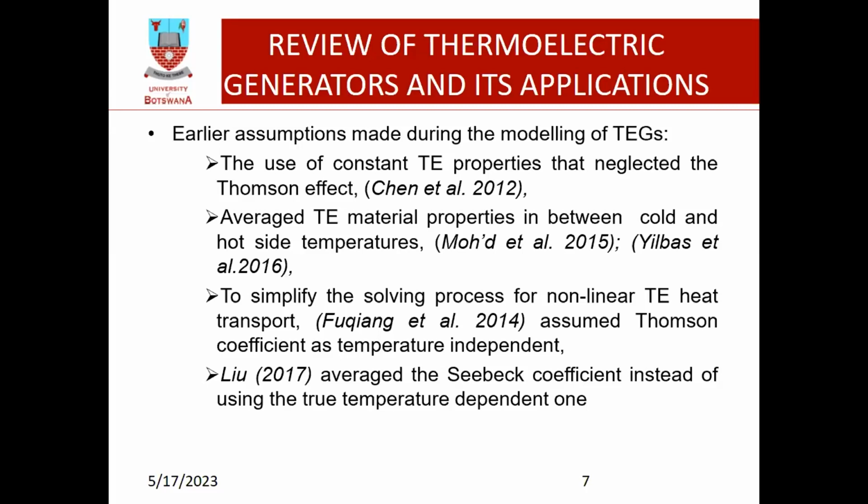One other model averaged the thermoelectric material properties between the cold and the hot side. Some other models assumed the Thomson coefficient as temperature independent, which in fact was found to be temperature dependent. And the averaged Seebeck coefficient was used in other models instead of the true temperature-dependent one.